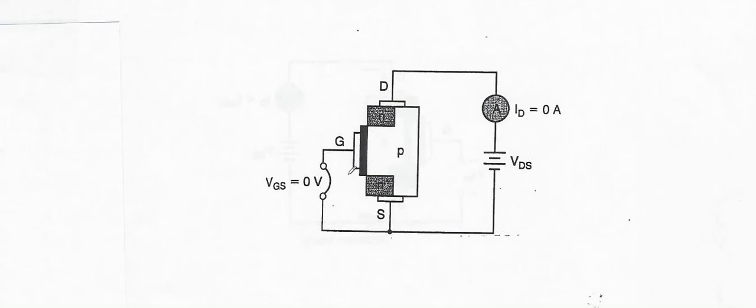And then on the other end of the spectrum is the E-MOSFET with 0 volts at the gate. It's completely off. The channel does not exist. A channel does not exist. And then kind of in the middle, you have the D-MOSFET with 0 volts at the gate. A channel exists that can be widened or narrowed.